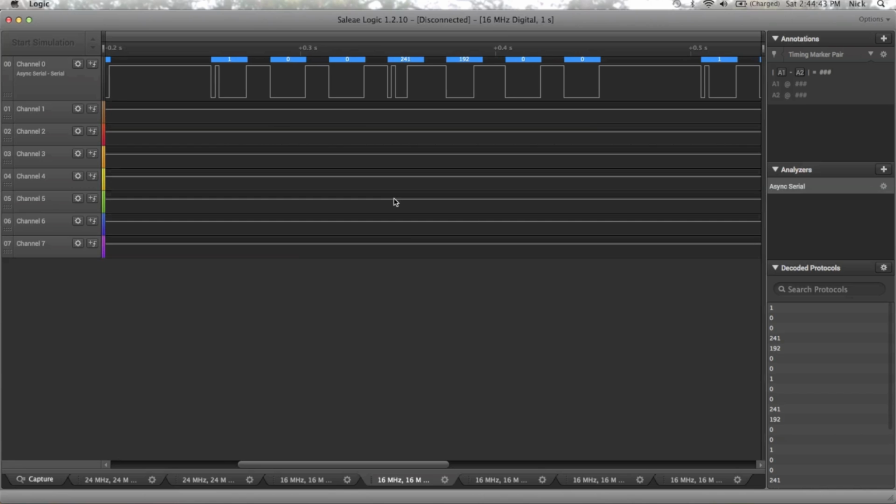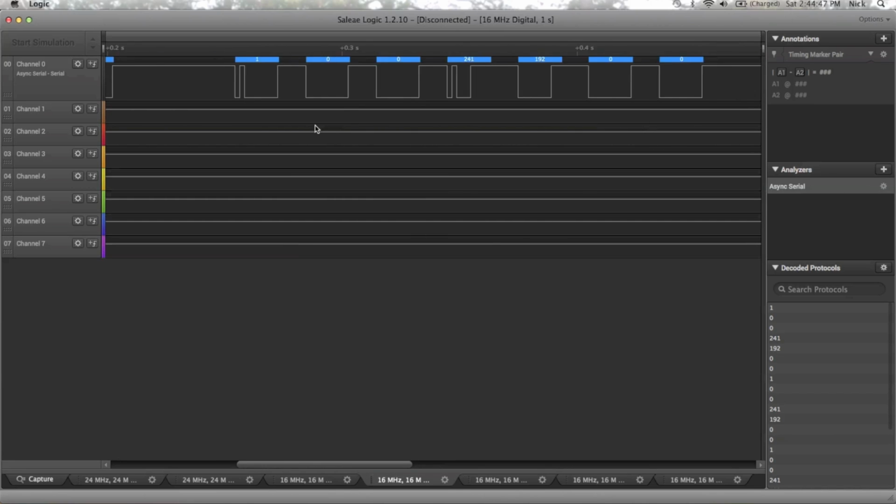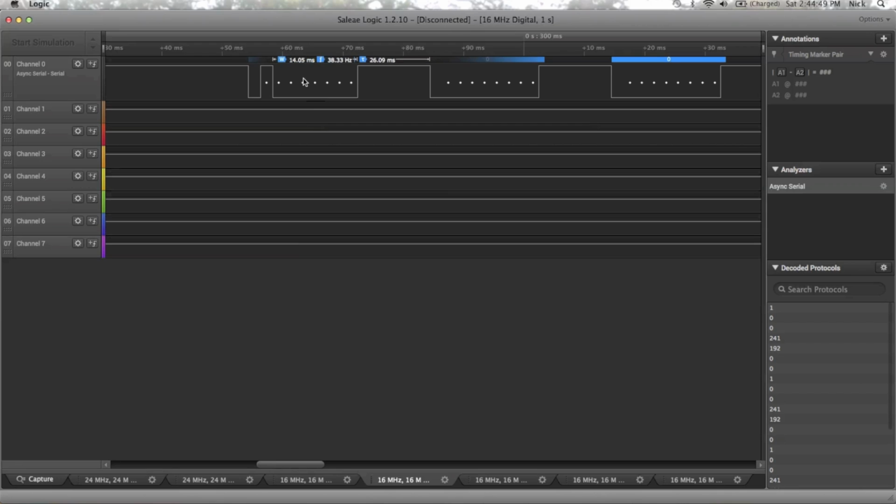Now if we go over to the transmission, there's a couple interesting things here. This is what I got from the transmission. This baud rate is ridiculously slow. I was not actually prepared for how tiny this is. Each byte is like 2 milliseconds. Compare that to the Jeep ECU, where each one was 16 microseconds. This is a huge difference in time. This is a really slow stream.